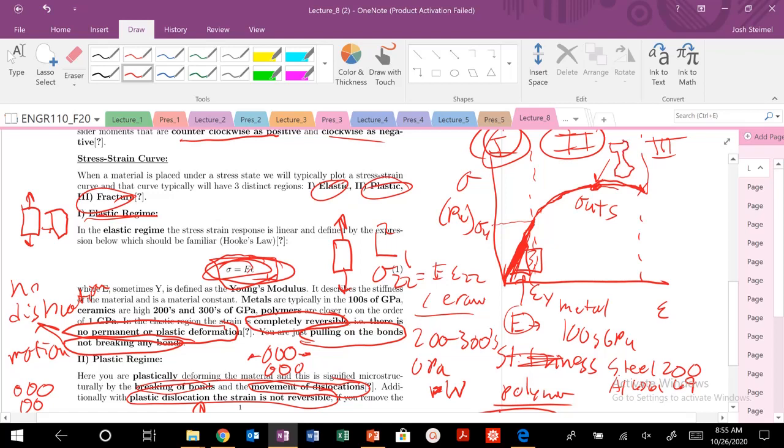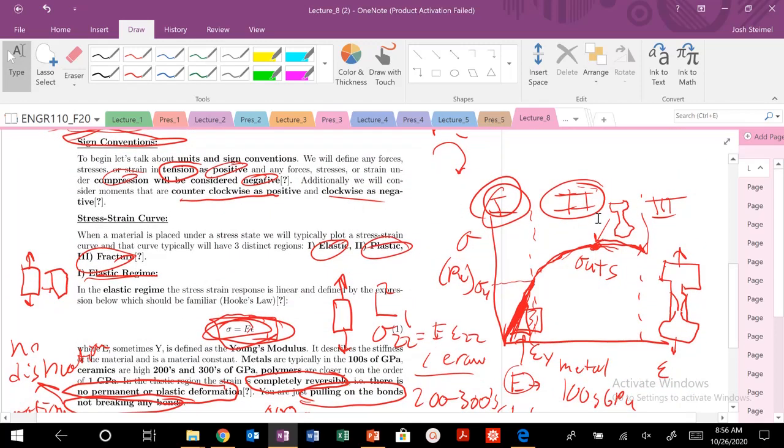Unfortunately, you can't see that in our lab component, but hopefully there will be a video soon that shows you the necking phenomenon. You typically have a sample that's a dog bone shape. When you pull, you eventually reach a point in the plastic regime where the neck starts to thin out, narrow and elongate. Where you hit that peak and then start to drop off, that's where necking is initiated. It's really cool when you see it in person. Finally, you can see sigma UTS, yield stress, and yield strain. This is also a measure of the toughness or strength of a material.